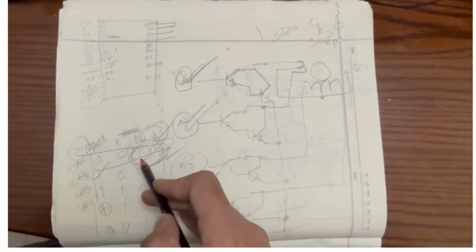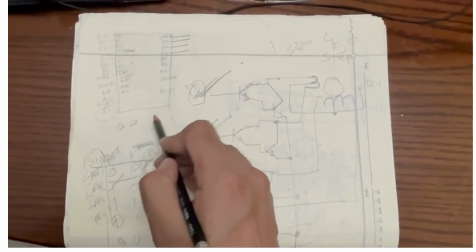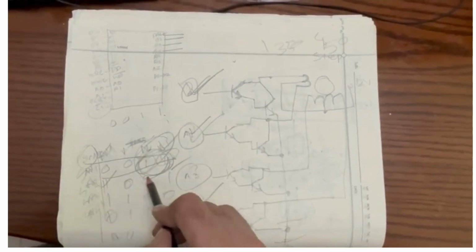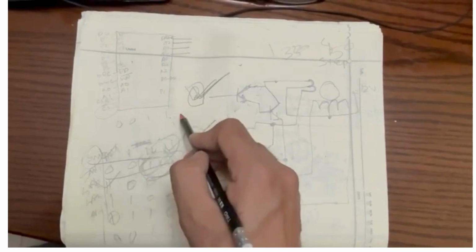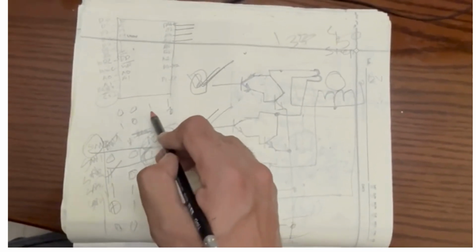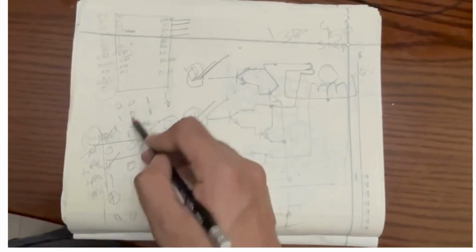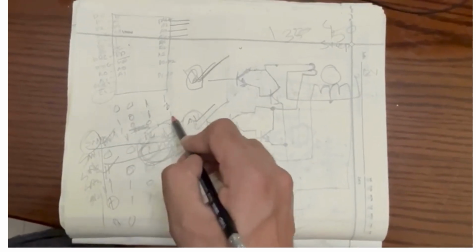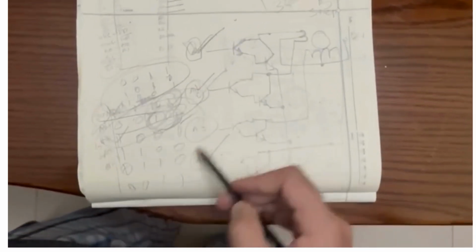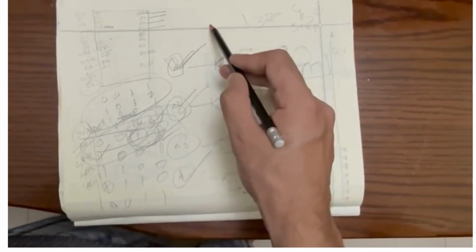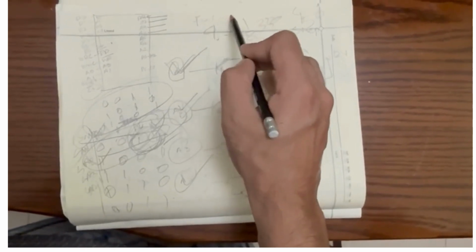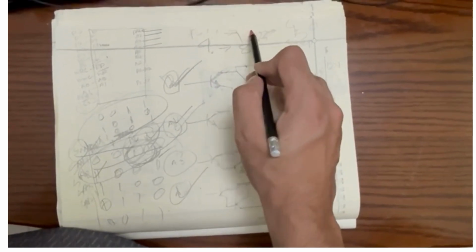But in half step we will only shift 1, in 0 0 1 1. In half step, instead of getting 1 0 0 1, because this 1 is over here and this is going on, just this 1 will go over here, 1 0 1 0. This will remain as it is. Next step 1 0 0 1. Next step this will shift. So instead of 2 steps, I am giving it 3 steps, and by doing all these things, these 4 steps will be converted to 8 steps. That is, the full step will be converted to half step.